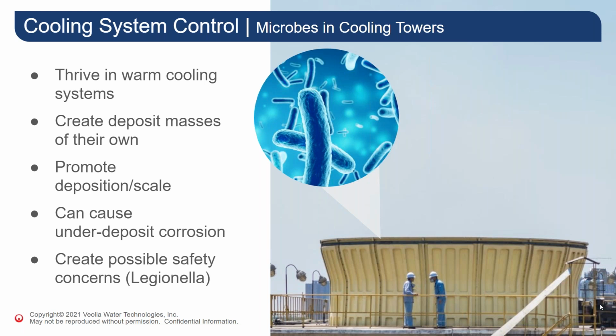The algae in the cooling tower will definitely disrupt the formation of that thin film of water inside the tower fill, which then reduces evaporation. But they also allow for the growth of other microbes such as Legionella, slime-producing bacteria, and sulfate-reducing bacteria. And the algae mats eventually can slough off the tower fill and flow through the recirc water to the heat exchanger, either plugging it or baking onto the heat exchange surfaces. This, of course, leads to poor heat transfer and then can lead to underdeposit corrosion.